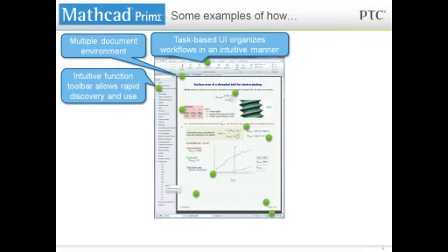There's an intuitive function toolbar. So all of the functions, the built-in math functions, as you know, Mathcad is a math engine at the core. So it has hundreds of built-in functions, and those functions can now be displayed simultaneously next to your actual document, so you can actually scroll up and down through the function library, expand topics. Okay, they're grouped into topics. You can expand the categories or expand the topics, find the function you need, hover over it, get immediate help, and so that panel can be displayed as you see here on the left-hand side, the right-hand side, or it doesn't have to be displayed at all, but you can display it if you want to.